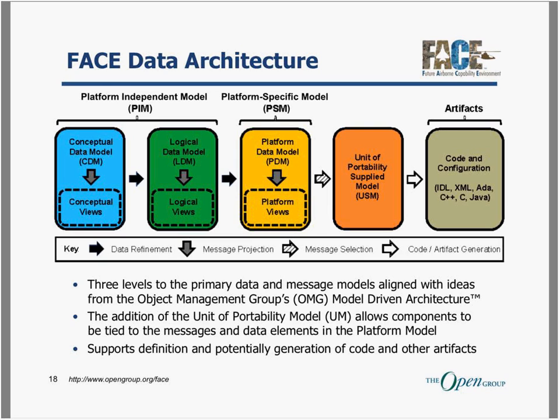I'll quickly go through this, but the conceptual data model is basically conceptual views of information that are not platform specific at all, such as air, sky, vehicle. We'll use data refinement to step to the logical data model view, where we start talking about observables and measurements that we apply and give more context to those conceptual views. This can project a message, and then we move to the platform-specific model. We can add in specific information related to the aircraft itself or system itself, and then actually create the message.